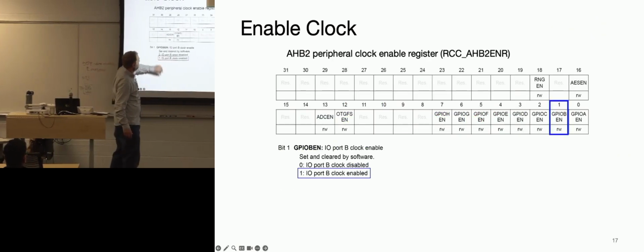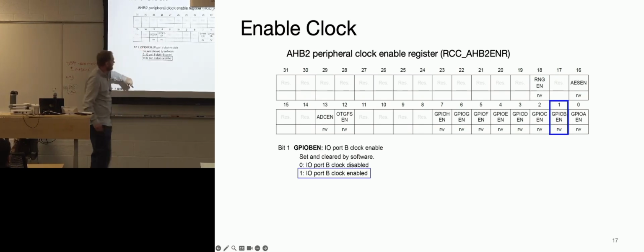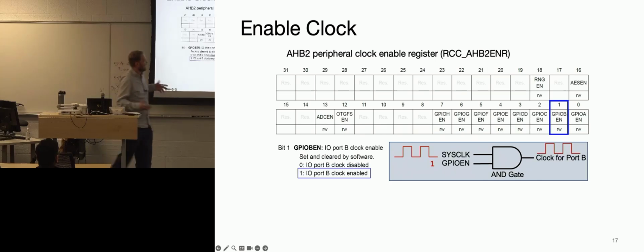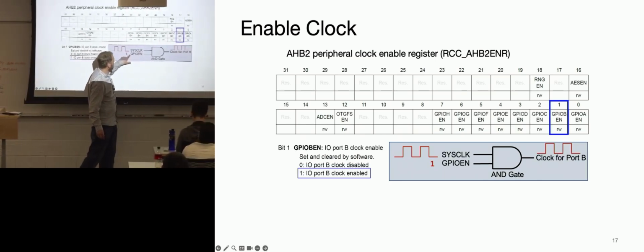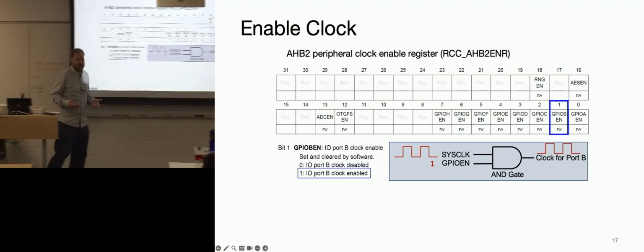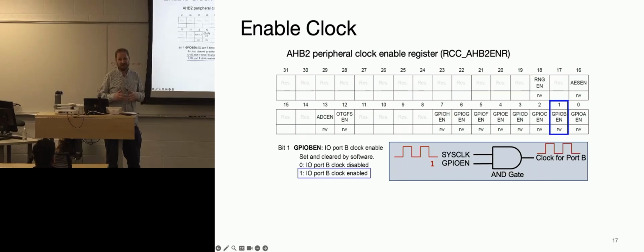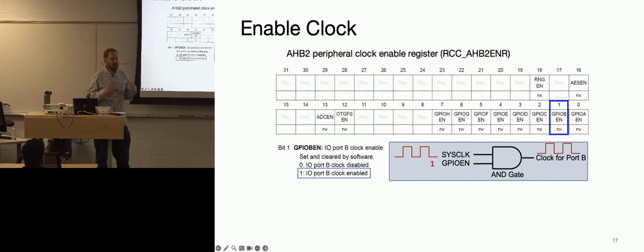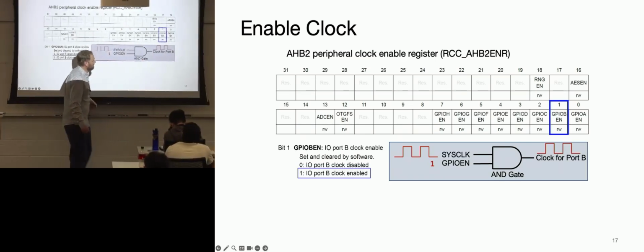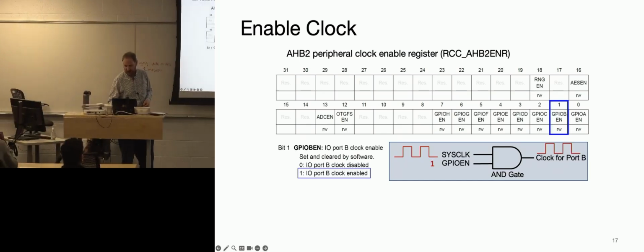You also have your clock enable bit. I bet you've been going through and changing your clocks. You can set it to port B, and you can enable or disable it. It's a cost saving or power savings thing. Having a clock run, especially on modern processors like an Intel processor, is so leaky now that having your clock on is almost the same as having your flip-flops moving, just because of how much power these things consume. So by turning off your clock, it's a pretty big power savings for that peripheral. That's why it's off by default.